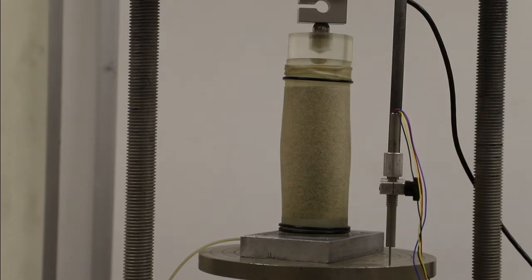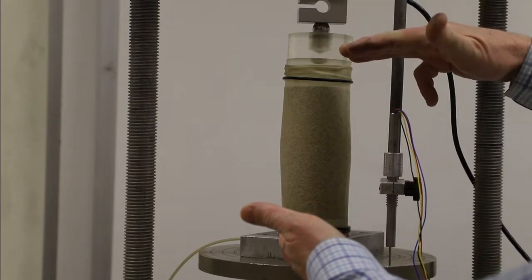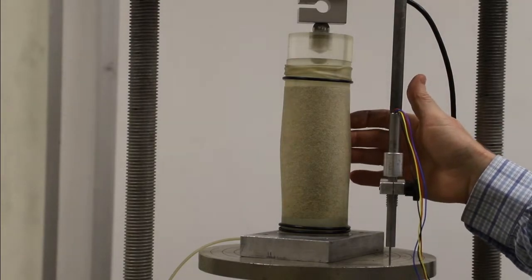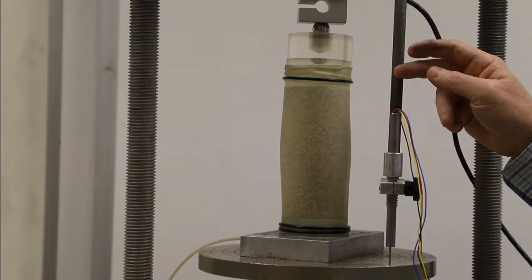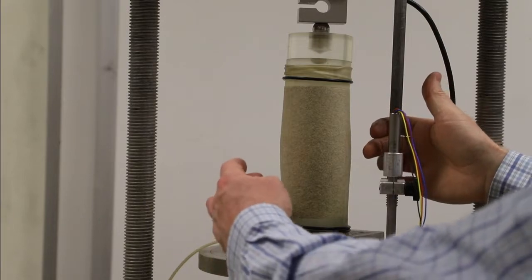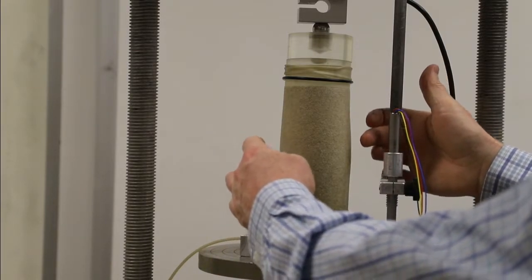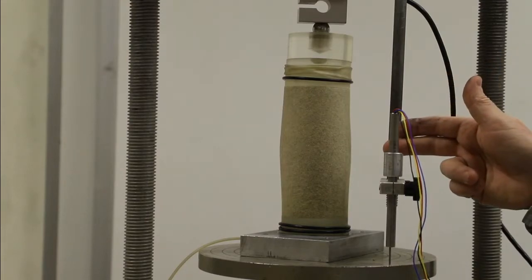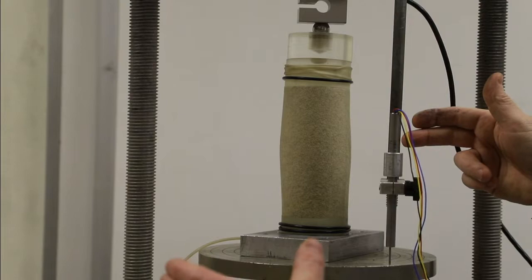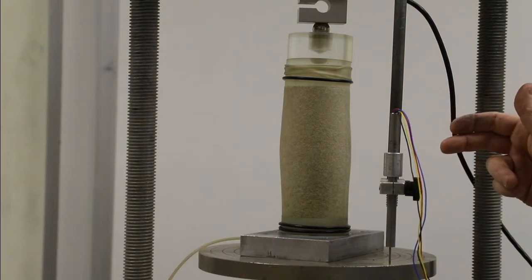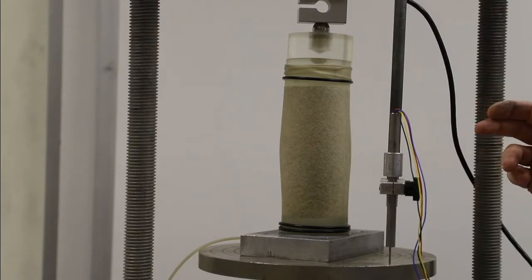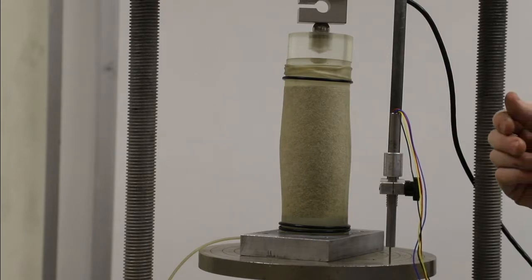We're getting a deformed shape where as we squeeze the sample down, the specimen is getting larger in diameter, but not uniformly. It's happening mostly in the center regions of the sample, the center maybe third to half of the sample. And so we have to recognize that as the diameter changes of the part of the soil that's shearing, the cross-sectional area is changing. And so we're going to need to reflect that in the way we reduce the data and make an area correction.